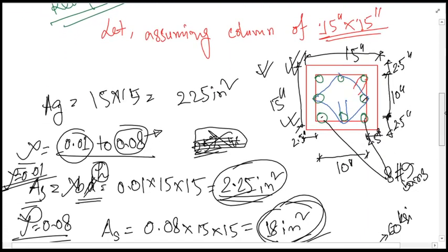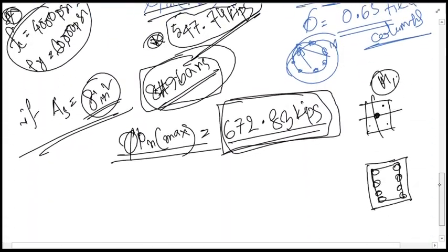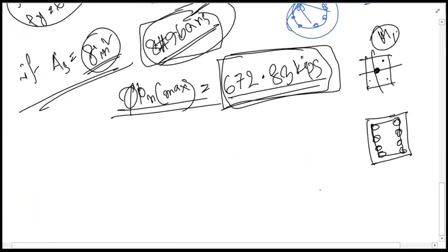We don't need this amount of reinforcement to withstand that, but still, as we know, the capacity will be reduced due to eccentricity, that's why we'll be calculating using the reciprocal method now. So let's use the reciprocal method first.